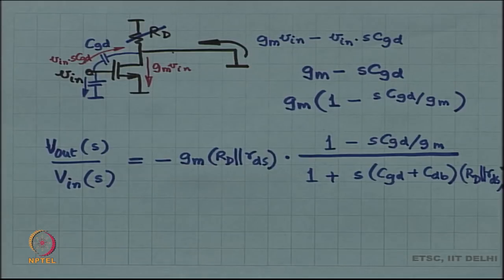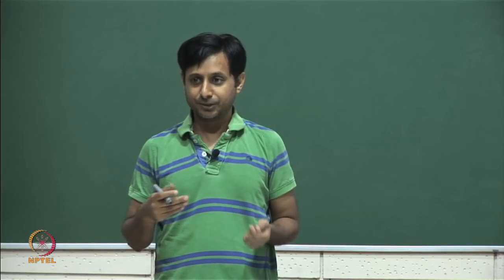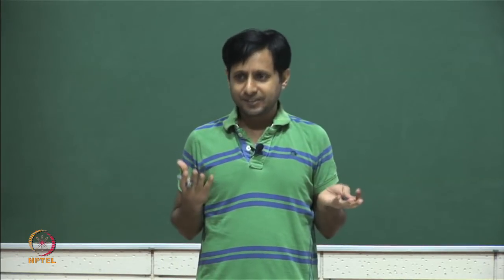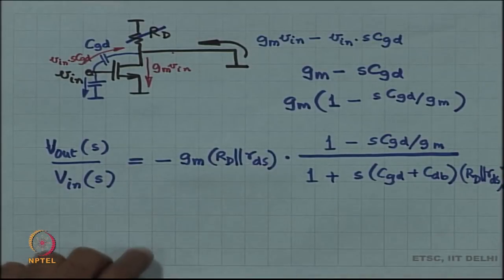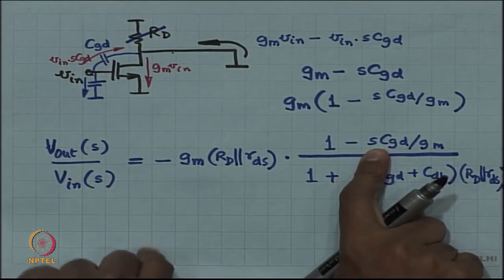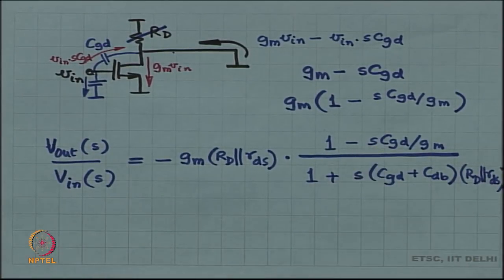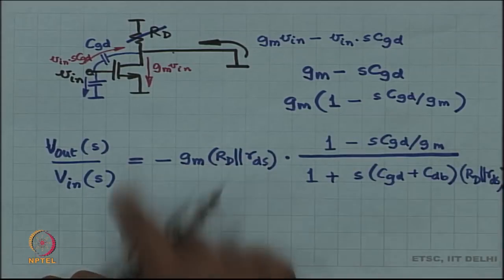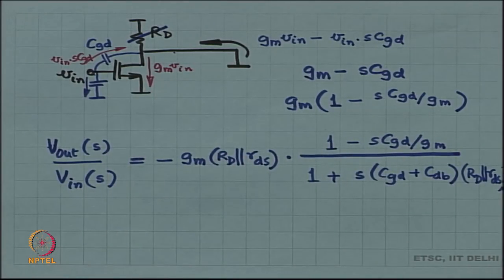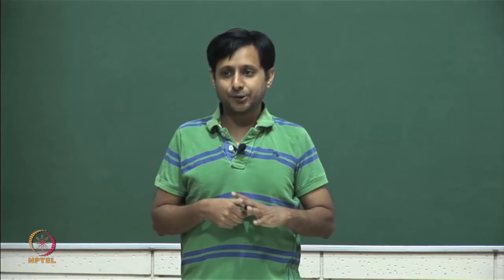Should I remind you how to draw a Bode plot? Bode plot had a gain plot and a phase plot. Okay. See, Bode plot is nothing but a plot of this, okay, replacing S with j omega. So, I replace S with j omega and I sweep omega and I plot this quantity. Now, when you try to plot this quantity, you are trying to plot a complex number, right. So, it is very hard trying to plot a complex number. You can plot real part and imaginary part, but it does not make much sense to a lot of people plotting real and imaginary part.